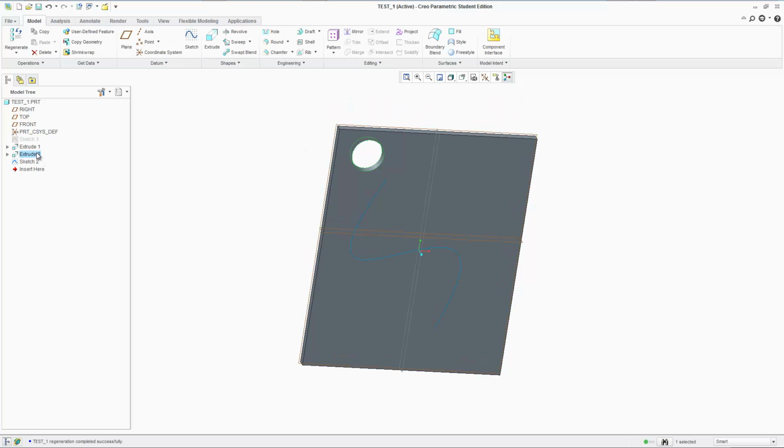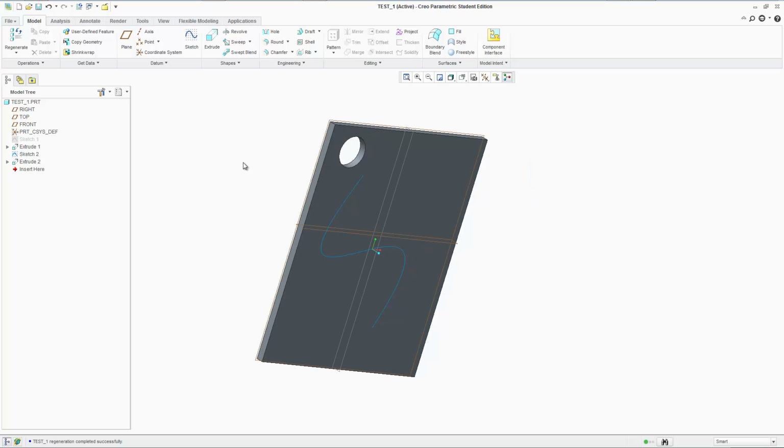See, this is hierarchy. So our extrusion happened before the sketch. So if you try to modify the extrusion, like having it patterned, it's not going to show anything that we did afterwards. So what I'm about to do is very bad, and don't do it. I'm just showing you how to do it. But this is just a sketch. But never just click and drag things randomly, because that could mess up your entire assembly or parts, and you could have a very bad day. Just make the sketch before you make the extrusion, and that's all I'll say about that.